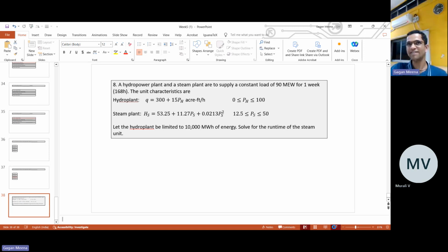You will find the generation of solar is maximum during springtime. At that time there is excess solar generation. During winters, you will find generation is very low. That's why the capacity factor of solar is not good. And with wind, which blows because of pressure difference, if there is high temperature throughout the country, the pressure difference is not much, then wind speed also reduces. So the output of wind is also affected in that case.